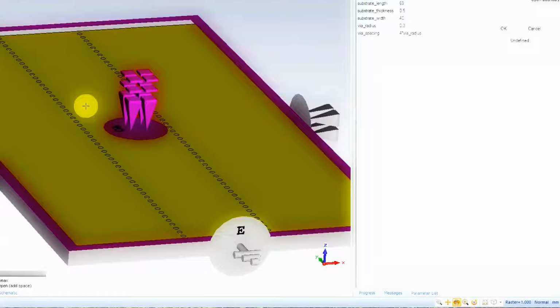In a waveguide simulation like this, it doesn't really make that much of a difference, but when you incorporate your SRW with other structures on the board, such as microstrip, for example, they would be interfered with if there was an electric wall, say, on the top boundary of the simulation, rather. So, to keep it consistent, I think this is just better. And the Ymin and Ymax are going to keep electric walls because I'm going to put waveguide ports there, and we'll see what happens there in a moment.